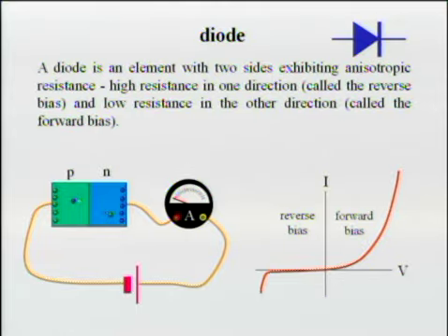They will produce an avalanche of carriers. So electrons will bump into atoms and knock out more electrons. Eventually, minority carriers become very numerous, and we have a kind of discharge in the diode. For a particular diode, it happens at a precise potential difference. Therefore, Zener diodes are used to stabilize voltages. This avalanche happens at a particular voltage.